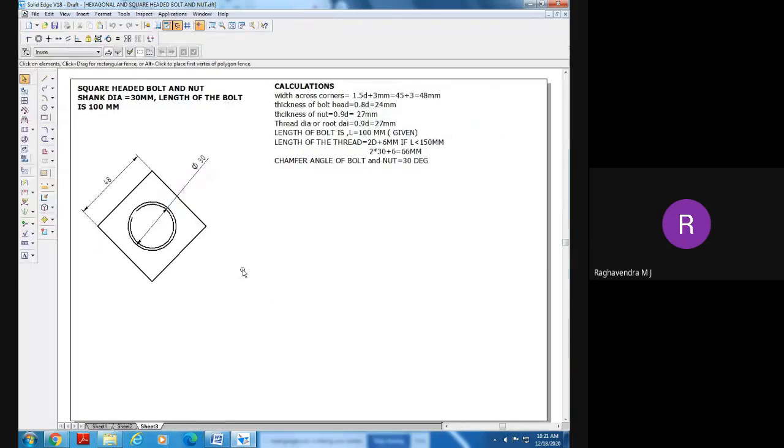Okay, so that we don't have any calculation. Simply go for the circle here. Take the center and draw the circle tangential to the flat surface of the nut. This completes side view. Any difficulty in this? No, sir. Any doubts? You can discuss here. In the same way, manual sketching also you have to do. There is no difference here.